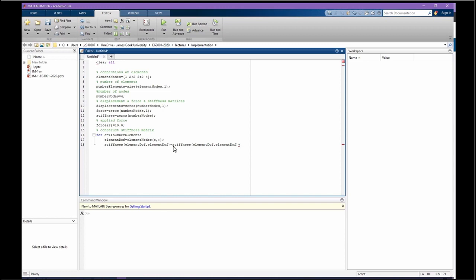And this is going to be 1, -1, the next row, -1 and 1. Done. So here I'm going to identify the connections and then tell stiffness matrix use those connections to modify the global stiffness matrix. I don't want to modify anything else.